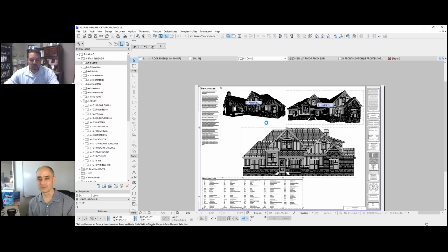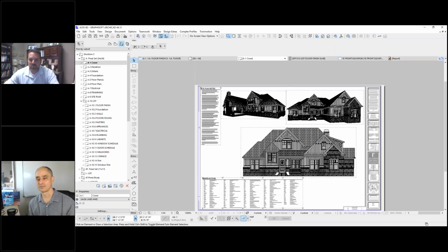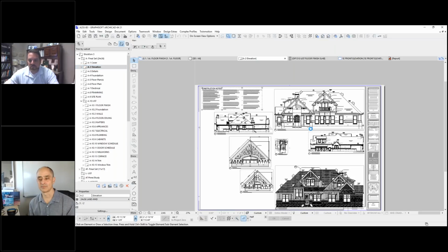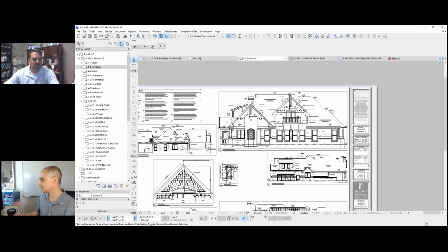Yeah, like I said, once it gets through updating, we do a typical cover sheet with a flat elevation and give some 3D perspectives on the cover sheet, and then within our elevations, we'll get into the detail aspects of the block, the brackets and gable details, all your call outs on your elevations.